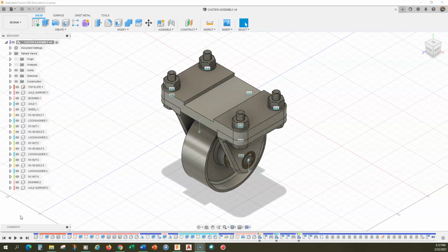All parts live in an assembly. And in order to properly dimension an individual part, you must understand where it fits, where it sits, where it lives in the assembly. If you don't understand this, then your dimensioning is going to be wrong right from the start.